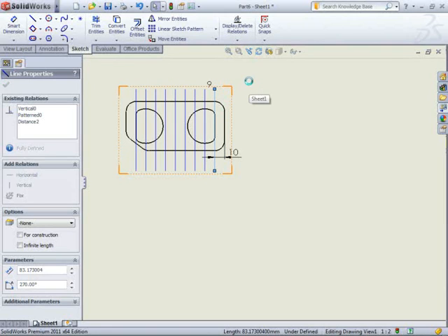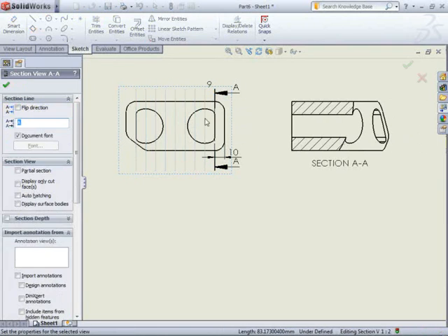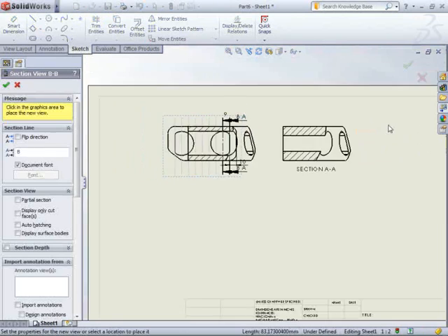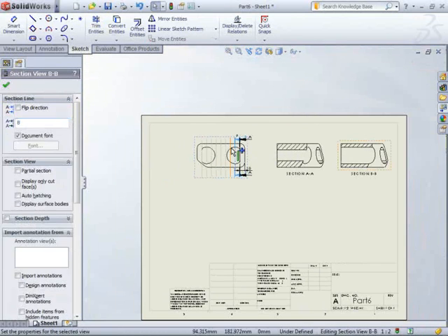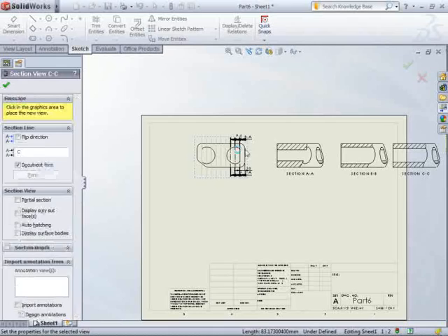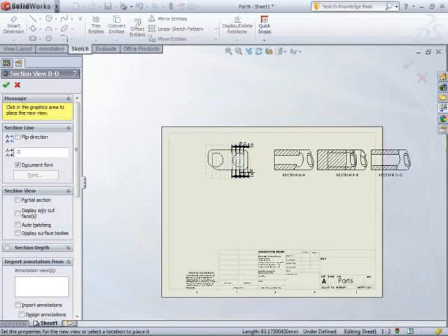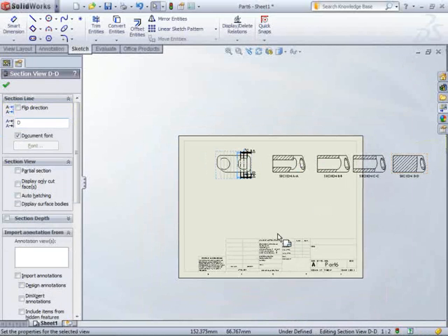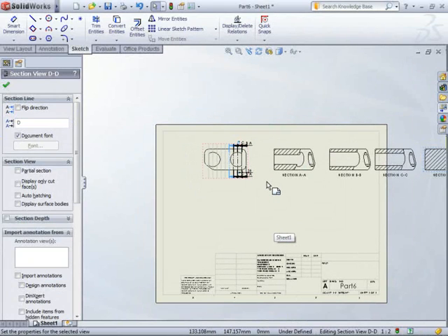I just select the line, hit L, it gives me a section view. Select the next line, hit L, it gives me a section view. L again, select that line, hit L, and so forth. And so that's going to make my life a lot easier. So you can see that even though this isn't something I need to do day to day, by setting up a keyboard shortcut for this particular task, it's going to make that repetitive task just that little bit quicker to do.